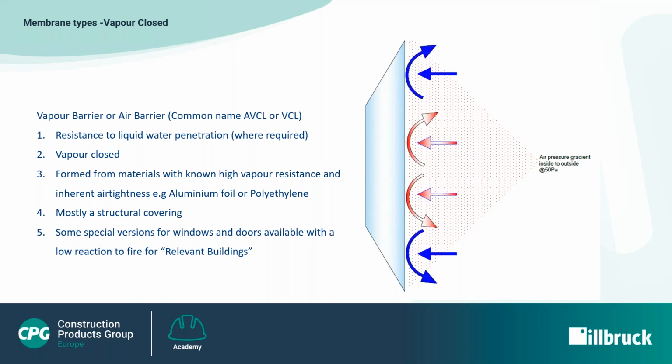It is the preferred solution for internal window and door sealing applications that require compliance with Approved Document B. ME480 is not used as a vapour barrier in the commonly understood sense of a VCL. It's a dedicated internal seal added to the perimeter and is then linked to the structure and the primary vapour barrier membrane. Together, they make up the vapour control layer. ME480 can also be used externally in special circumstances.